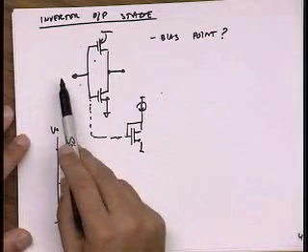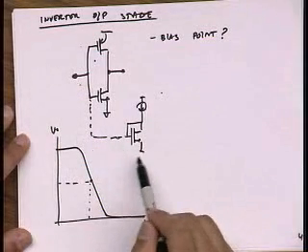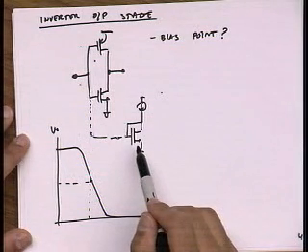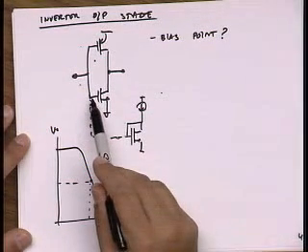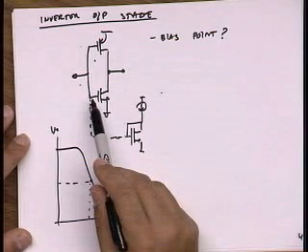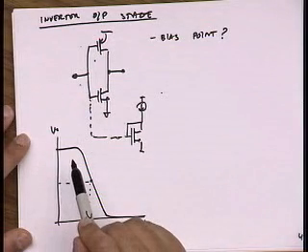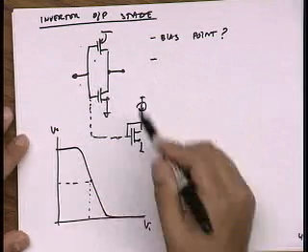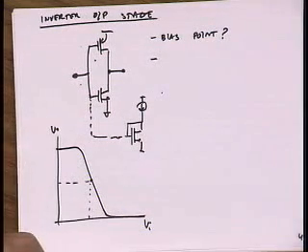Now if I apply an input signal, I have a diode here, right, to ground, low impedance, and now it's going to be hard to drive the stage. What are some other issues? Well, we'll come back to this biasing issue and address it.